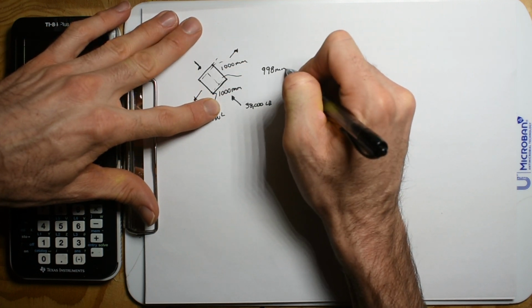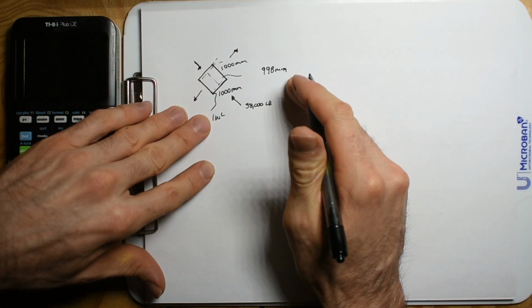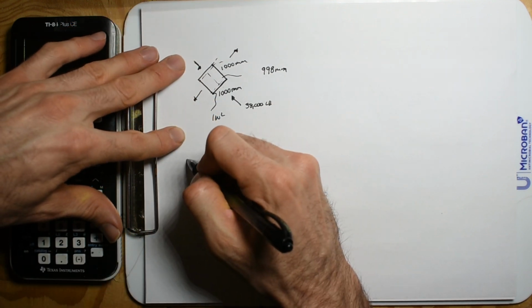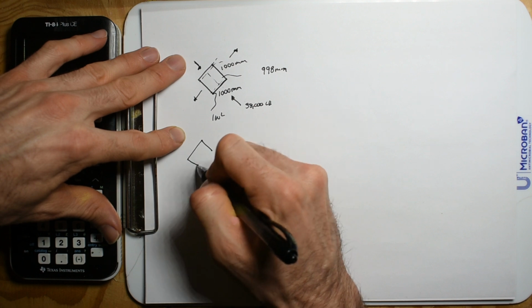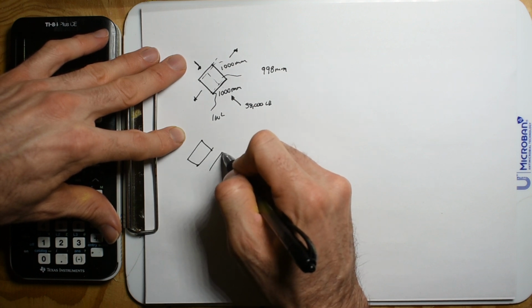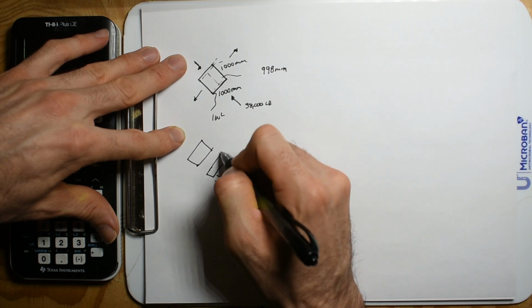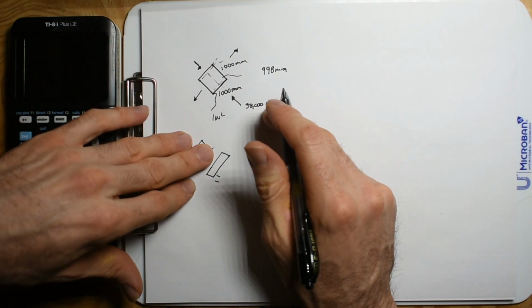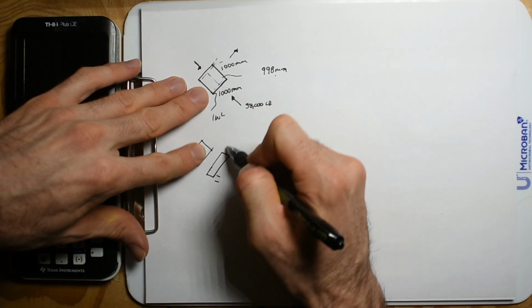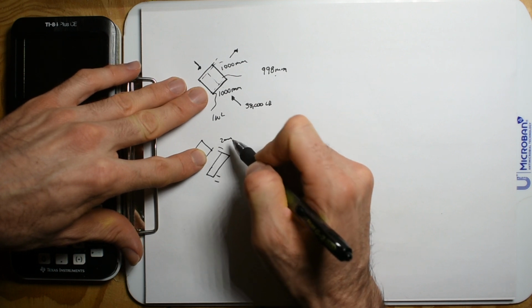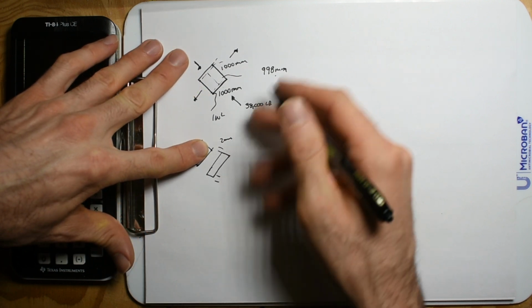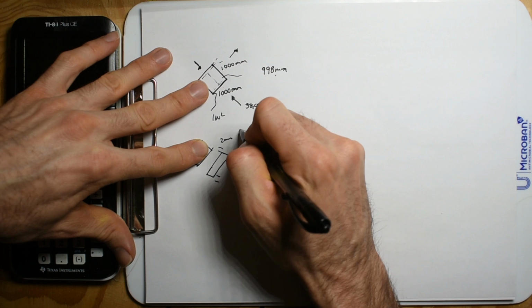This length now is going to be 998 millimeters. And when we do that, Poisson's ratio says, hey, we took something that looked like this, squished it, so now it is narrower, but it gets longer. And it doesn't get longer in equal proportions. You know what I mean? We squished it by 2 millimeters. Does it change in this way by 2 millimeters? No. But it's about a third. You know what I mean? And for steel, it's 0.3.